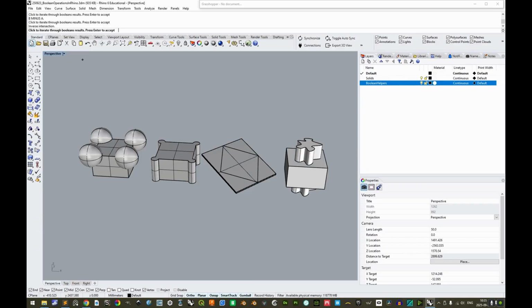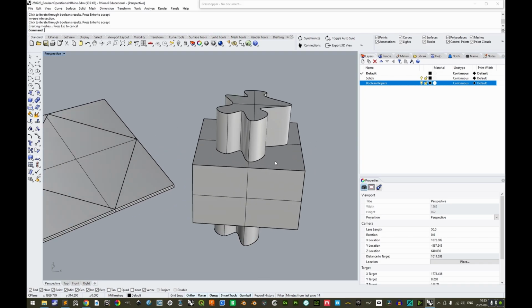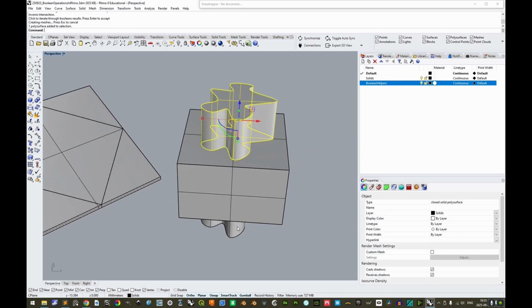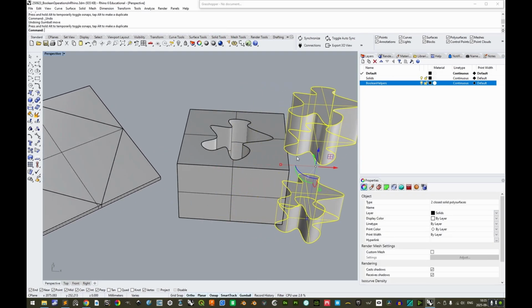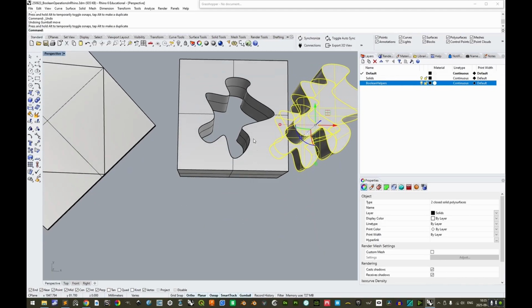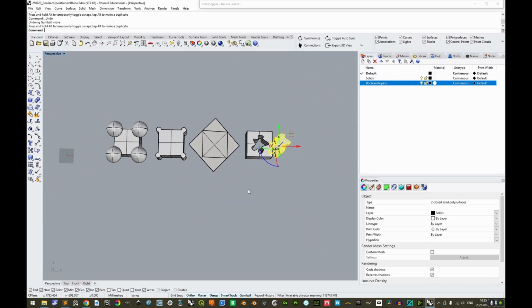Clicking once more, we'll get an inverse intersection. And the inverse intersection, we can actually stop here. The inverse intersection is the last option here, and to showcase what has really happened here, we can hit space or enter to confirm this. And with an inverse intersection, the volume of the cube has been subtracted with the volume of the extrusion, but the extrusion has also been subtracted with the volume of the cube, giving something like this.